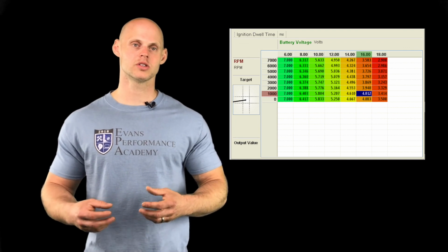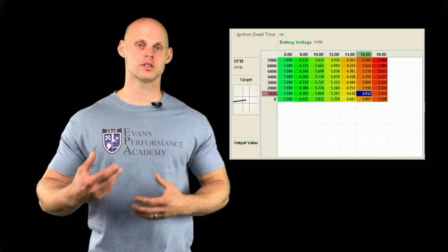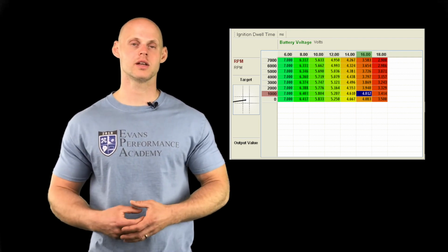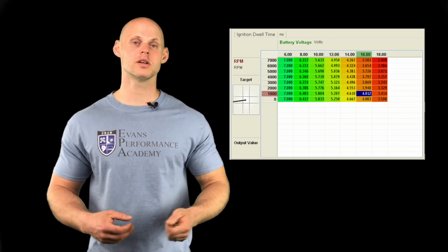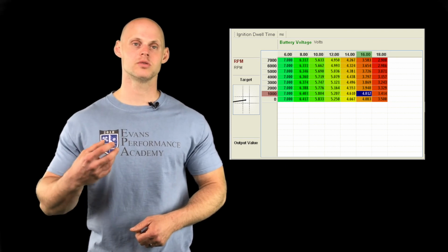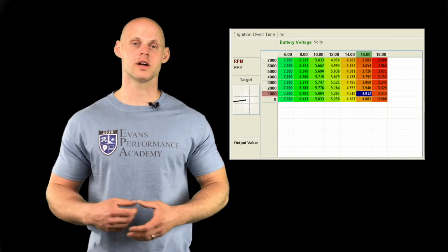So just note that in the future, when we're doing our system-specific videos, we're going to be talking a little bit more about coil dwell, how to program it, and what we can program. Some systems are going to be limited, and some systems are going to have a lot of flexibility and ability to program and control the dwell very precisely in our inductive style ignition systems.